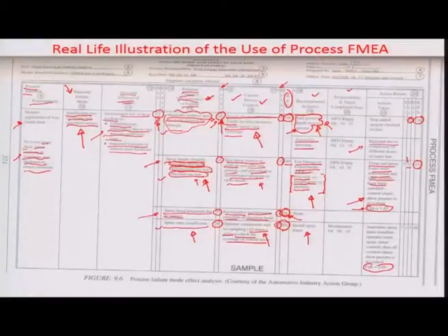And so in this case one records that from 70% the occurrence has come down to almost 10%, and the RPN is reduced to close to 49 from 392. So this is definitively a process improvement where the occurrence has reduced with probably the same degree of severity and maybe a slightly higher detectability limit.